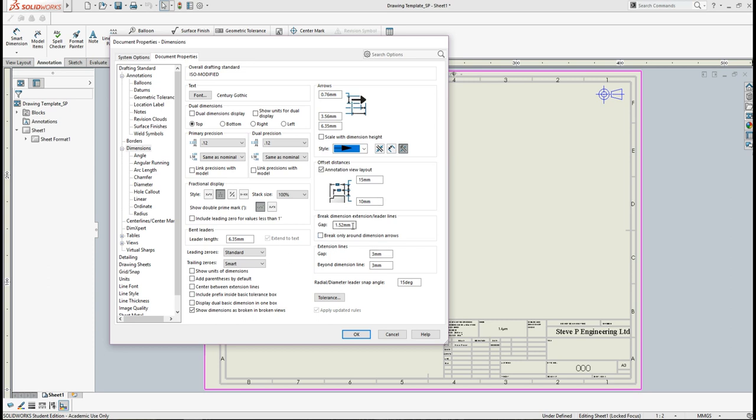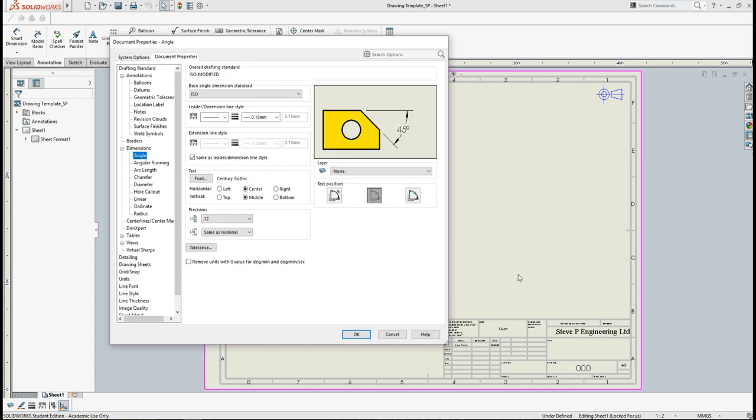We're going to alter this one just for you to see how to alter something. So I'm going to break my dimension line. So where dimension lines cross, I can actually have a break around that. So I'm just going to alter that to 3 mil. Just click there. Break the dimension. My gaps are set up, my extension gaps. My gap here is 3 mil, my tail is 3 mil, and so then my dimensions are, again, the style in which I lay dimensions out.